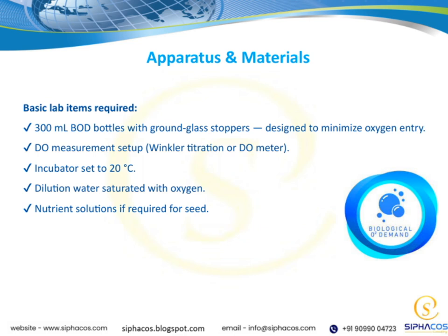Then, we require an incubator set to 20 degrees Celsius to maintain a consistent temperature during the incubation process. It's also important to have dilution water that's saturated with oxygen, so your measurements remain accurate. Lastly, if your experiment involves adding nutrients to seed samples, you'll need nutrient solutions on hand. All these items are essential to ensure your experiment runs smoothly and yields reliable results. They form the foundation for accurate and consistent BOD testing, which ties back to our overall goal of assessing water